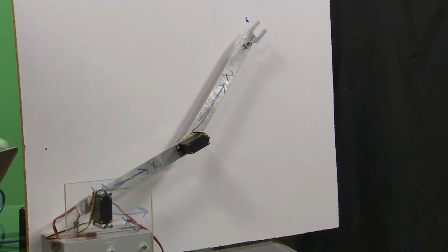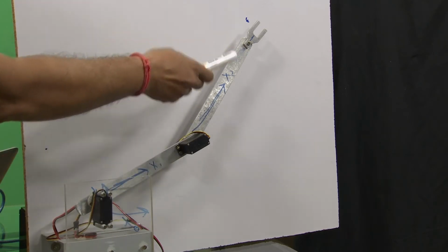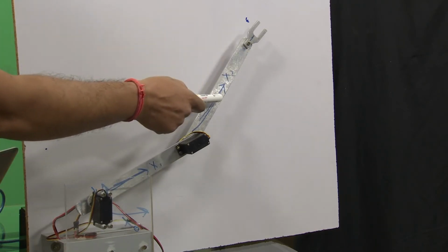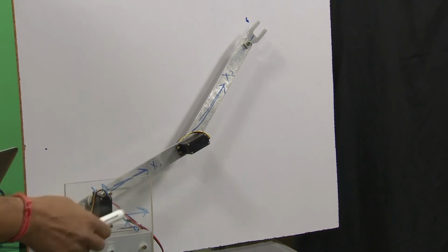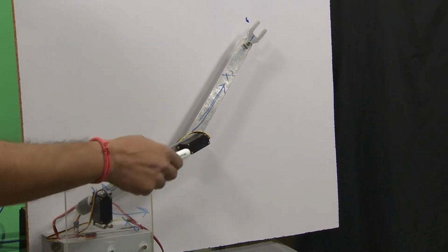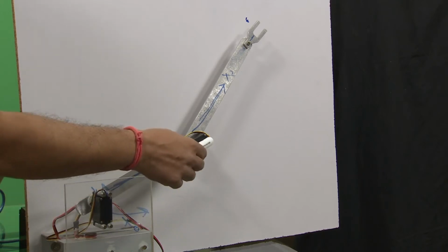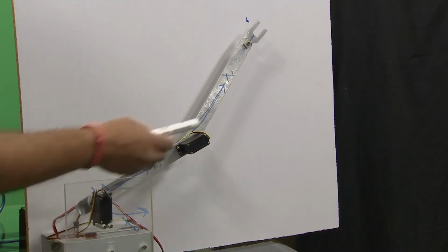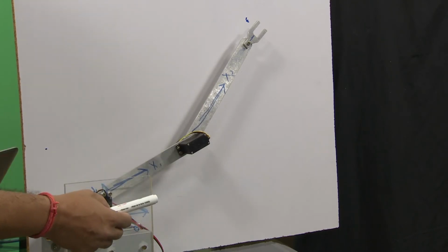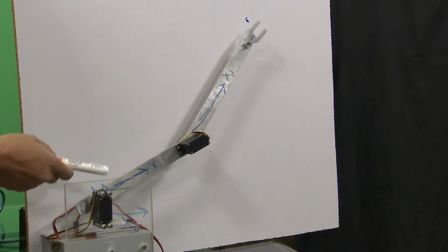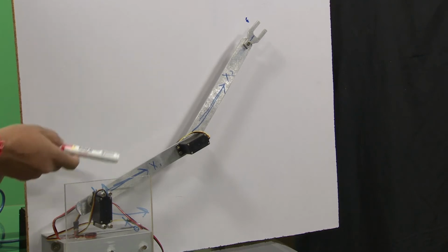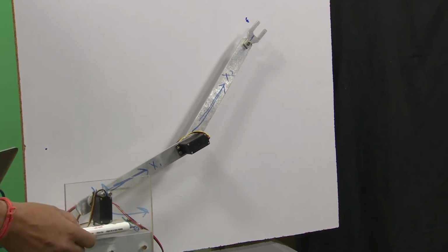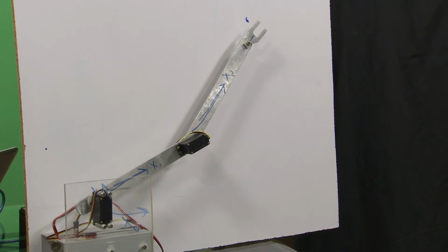Now if you see what is the difference between the frame 0 and the third frame, this third frame here or the second frame here essentially has translated. The origin of this frame has moved from here to here. It is at this distance now, so it has translated from here to here. And the second is there is an angle between this x2 and this x0. So this frame has an angle and a translation distance with respect to this frame. This frame has only an angle with respect to the frame 0. So essentially this shows that we need to know two transformations. One is the rotation transformation and the other is the translation and rotation transformation.